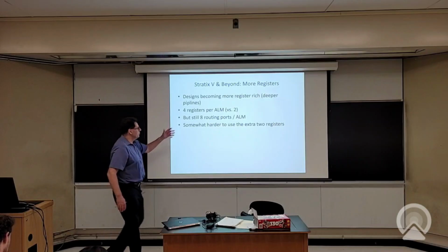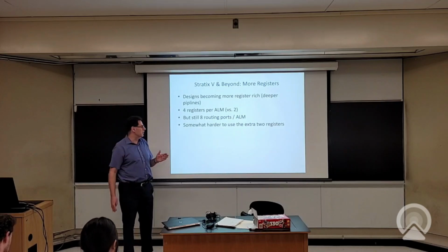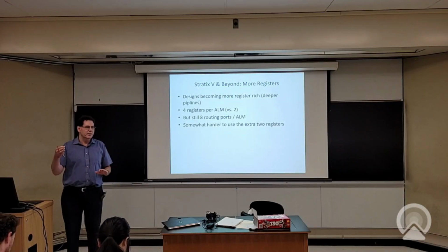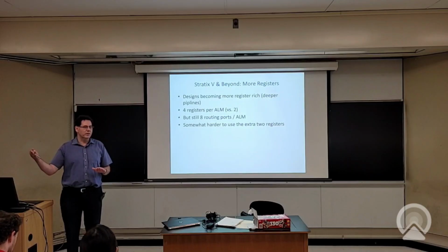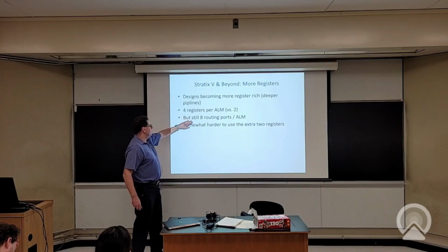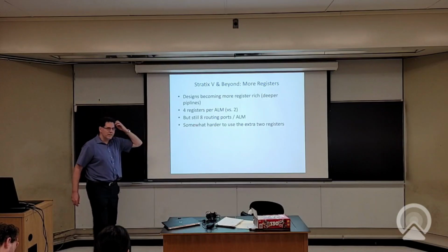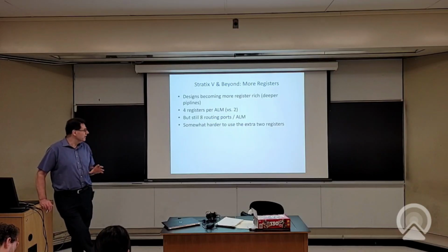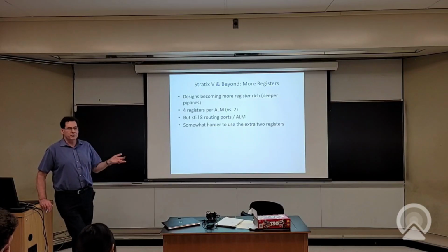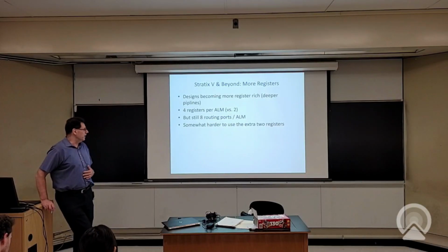So you wind up with some shift registers usually, where you have registers feeding other registers because you had to cut those paths. You might even have multiple registers in series because you need to get across the chip, and that actually takes multiple clock cycles, even with no logic. So this went to 4 registers per ALM, but still has 8 routing ports, and it is making it harder to use these. To use all 4 registers and use the LUTs becomes kind of difficult, because they are all fighting over these routing ports, but sometimes maybe you won't use the LUTs in those cases.